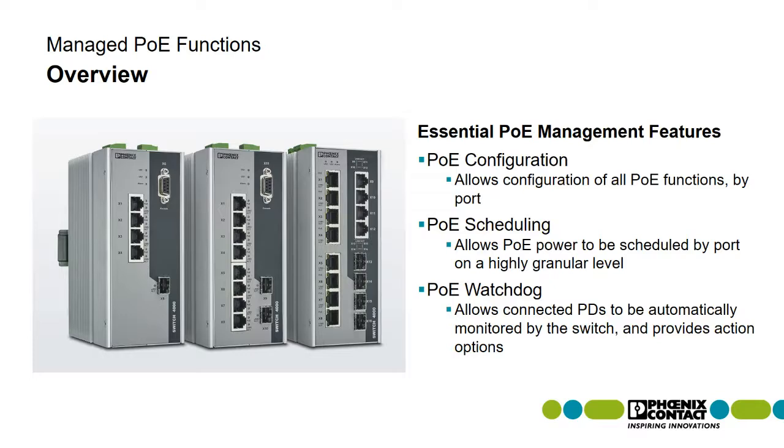And this can become very important for cost savings. If there's a location, a plant that, let's say, is only running one shift and they have a number of PoE devices, well, you're not going to want to have those devices active and powered on while nothing is running in the plant. So instead of shutting systems down, it gives you the ability to shut power off to the devices when they're not in use. So it gives you less power consumption and increased savings in that regard.